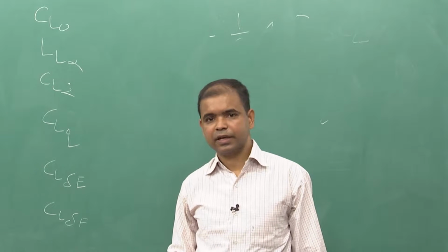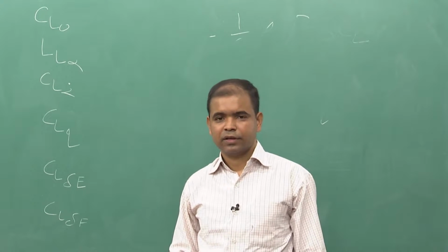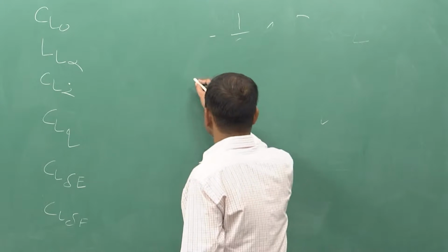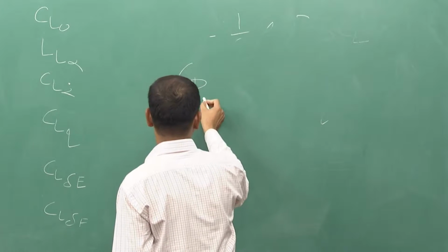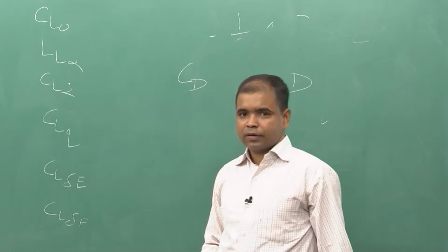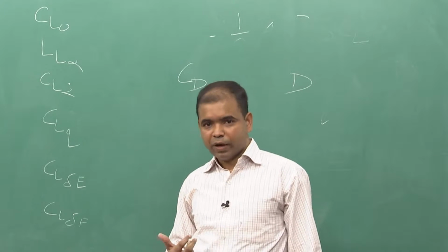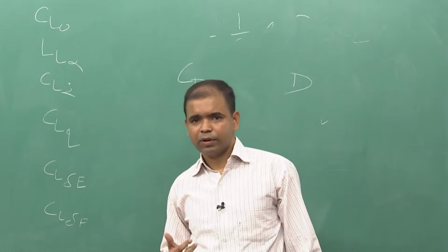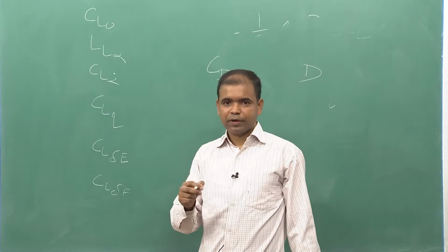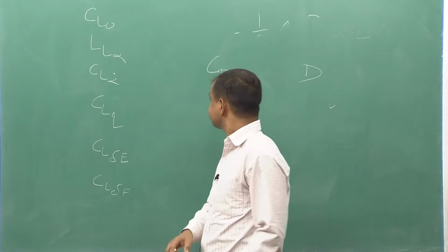CD delta F, CD delta A, CD delta R, and all other remaining coefficients, and from there you can find the CD, and once you know the CD you can find the drag, and you can find the Y forces also acting on the aircraft. Once you have all the forces, you can decompose them into body frame X, Y and Z axes.